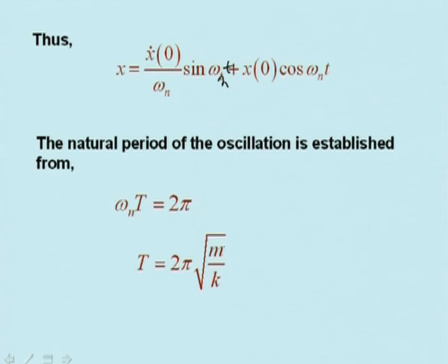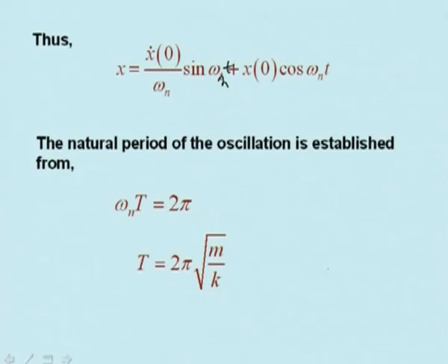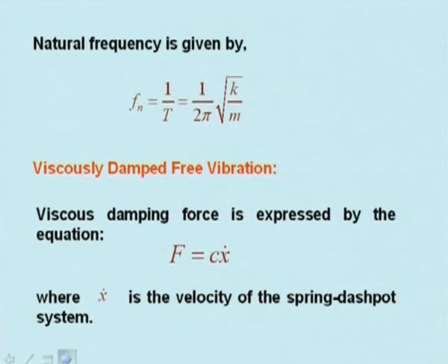If you take a spring mass system and suppose the spring is very stiff, k is very high, then the time period will be almost 0. That means the motion will immediately come back to the same position. So the time period is 0, it vibrates, and if k is very small, then the time period becomes very high. Similarly about the mass.